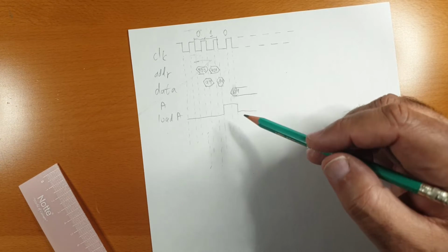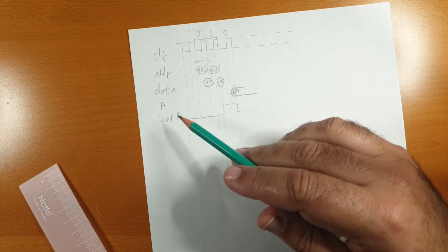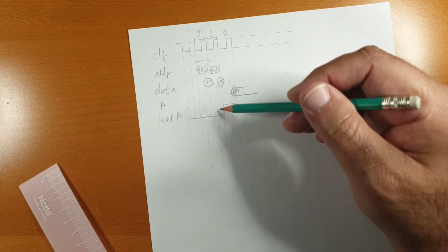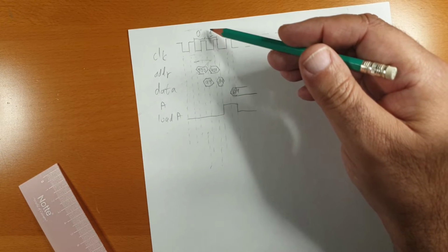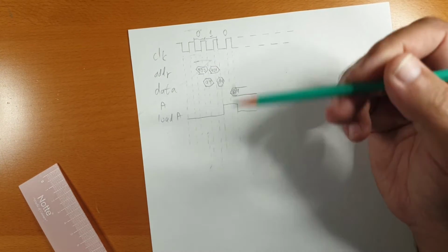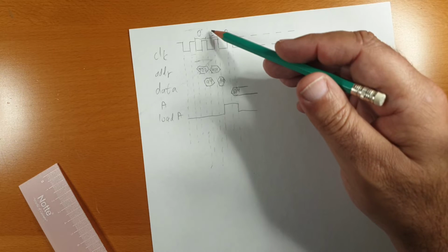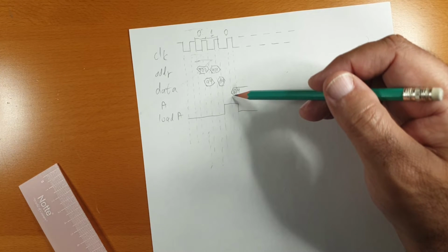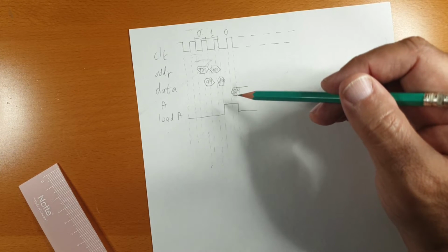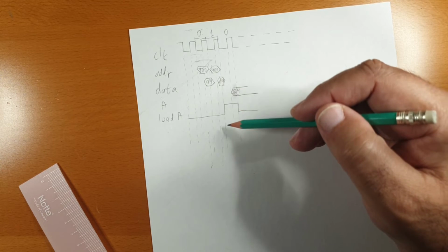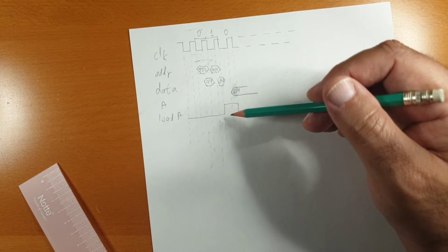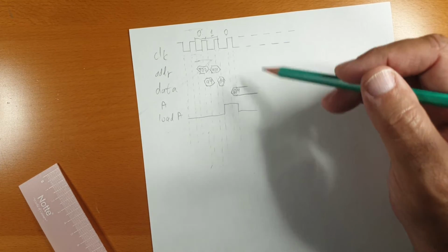This is a bit confusing, but it's pretty consistent for all control lines. Since the control lines are latched, what we say on cycle 0 will only take effect during cycle 1. What we say on cycle 1 will only take effect on the first cycle of the next command over. So on cycle 1, we say load A, and it actually loads in the middle of the next cycle over. Actually, this isn't as confusing as it sounds because everything gets delayed. So on the decoder, we give a bunch of commands, they all get executed together, and while they are a cycle off, it doesn't seem so from the code. Here, let me show you.